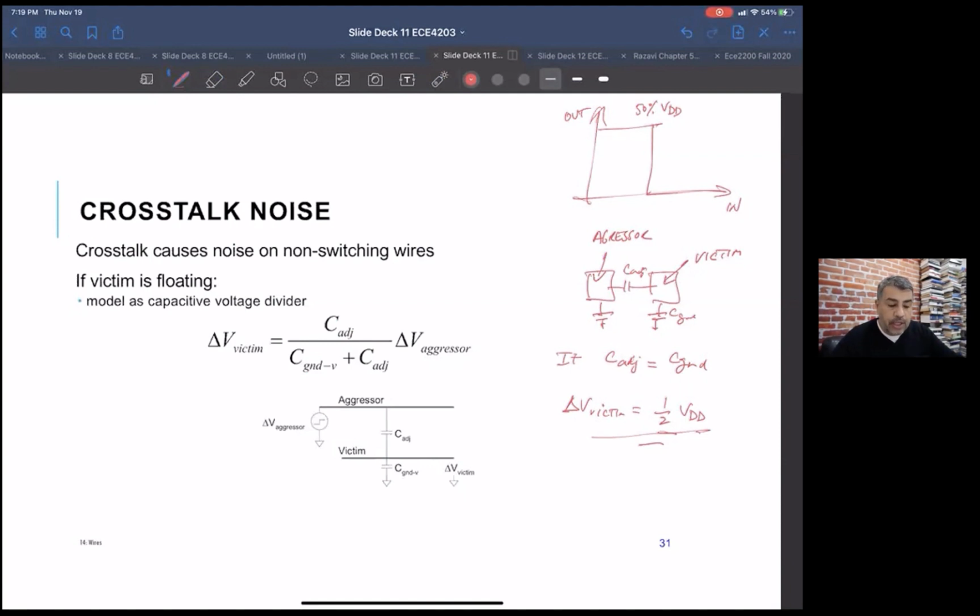That's why, when we looked at these pass transistors for latches, if you guys remember, in fact, we had one of these in our test. When you store, this is why this is such a bad situation, right? You've stored a value of a 1 here, which is already not as good a 1 as you'd like. It's not VDD, it's VDD minus a V threshold. And it's floating now.